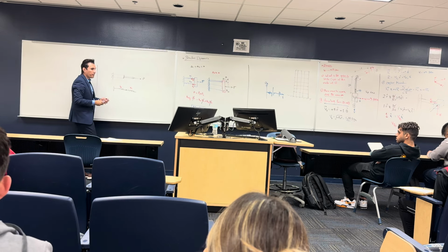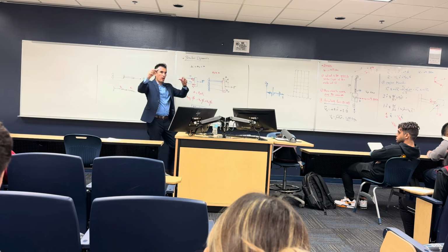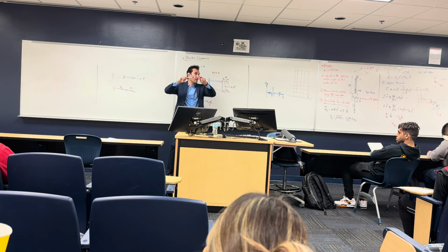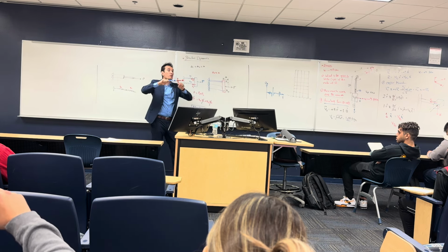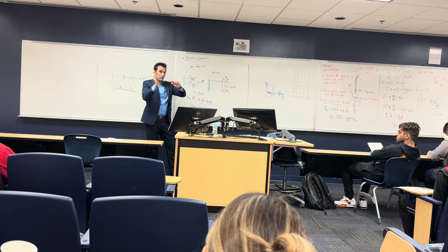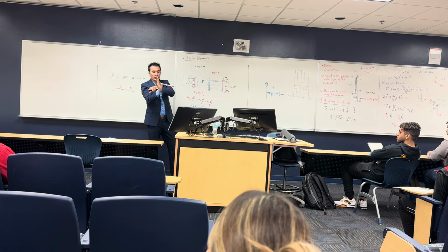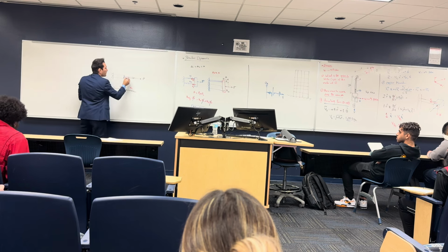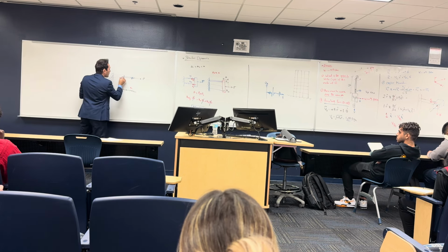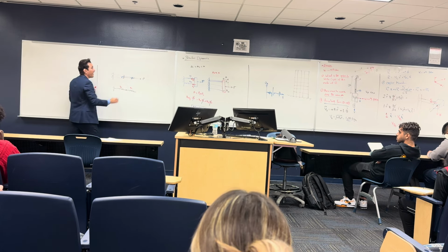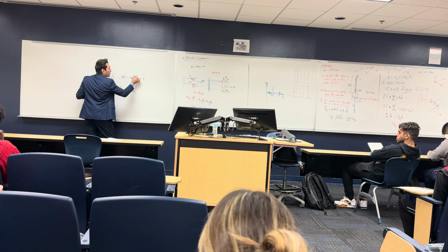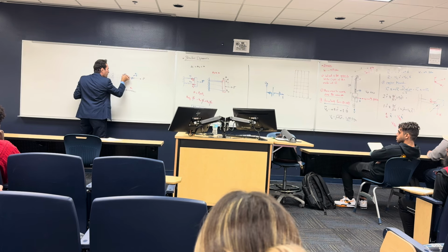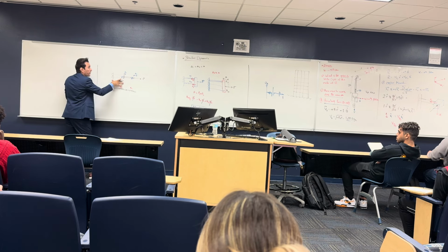What happens here, if you have two bars, this is a bar and this is a bar, attached to each other. One has K 100 and this one has 50. And you push them with force P. Both of them have the same force. Right? This is force P, and actually the reaction is P, so the force P is constant in both of them. So this one is going to have P, and this one is going to have P. But what happens is, this one is going to have delta 1, maybe something like this, and this one is going to have a very, very small delta 2, because it has bigger stiffness.